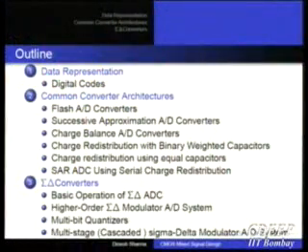We begin first by data representation, because if you are doing A to D conversion, the analog quantity needed no representation. Here is a voltage or here is a current. However, if you want to convert it to digital, then you need to know how to interpret various bits of the digital form. And this interpretation happens to be somewhat different from what we are used to. Therefore, I make it a special point to introduce it in advance, because most of the A to D literature, unfortunately, uses somewhat incompatible conventions for representing bits.